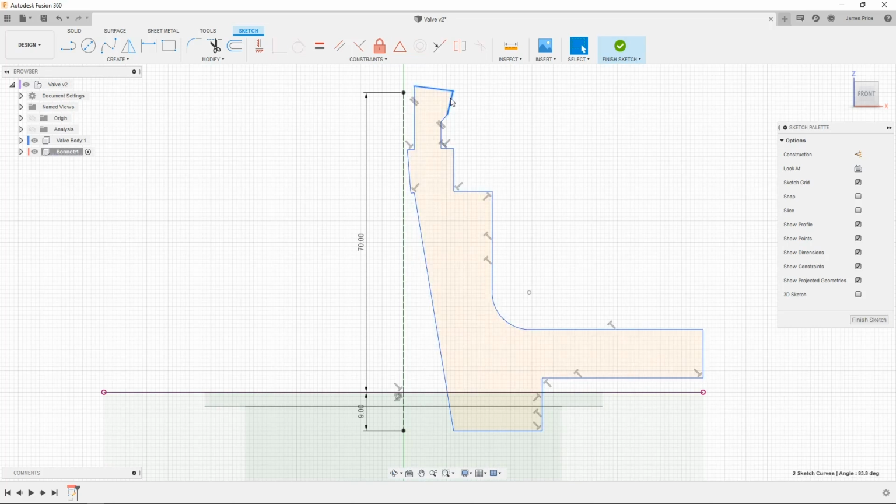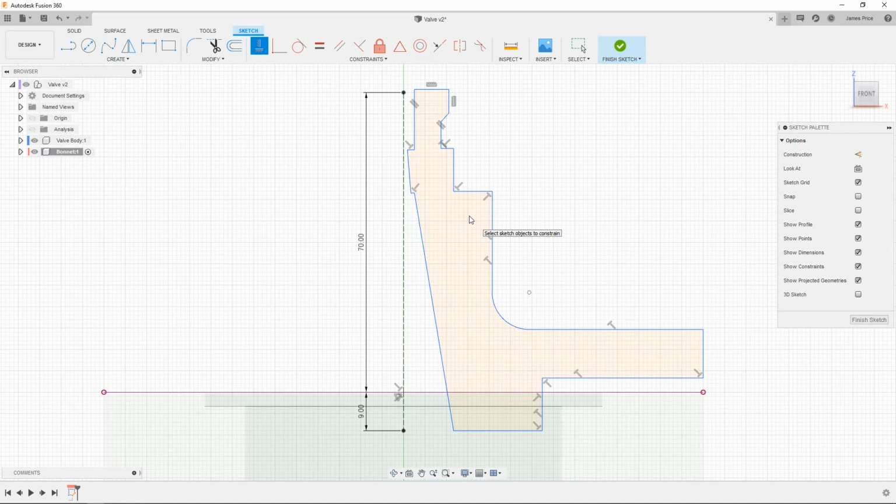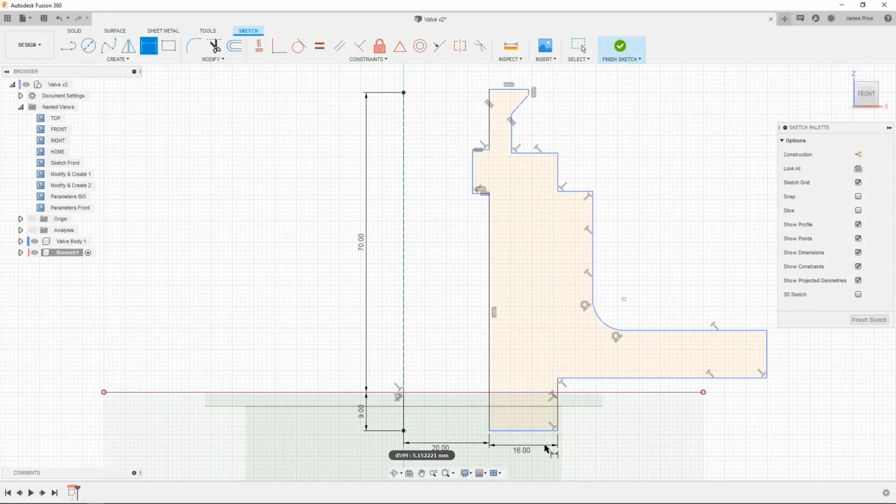One quick tip here is if you select two sketch features and right-click, you will only see constraints that are respective to those sketch features, which can help save you some modelling time. Alternatively, you can apply any number of constraints via the toolbar, as well as sketch modifications including fillets and offsets, and dimensions, also known as smart dimensions in SolidWorks, by either selecting the command or the features first, then applying until you have a fully constrained model.